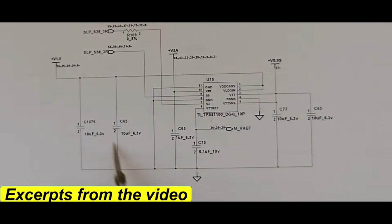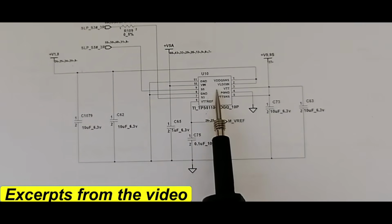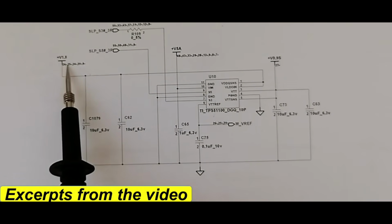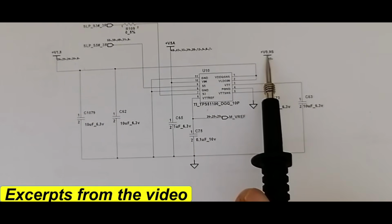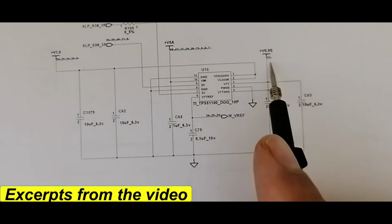For example here, this is the schematic. This is the IC that powers the VTT for the RAM. Here we have the main voltage, as you can see, 1.8 volts. And over here we have 0.9 volts. So the voltage for the RAM and the voltage for terminals